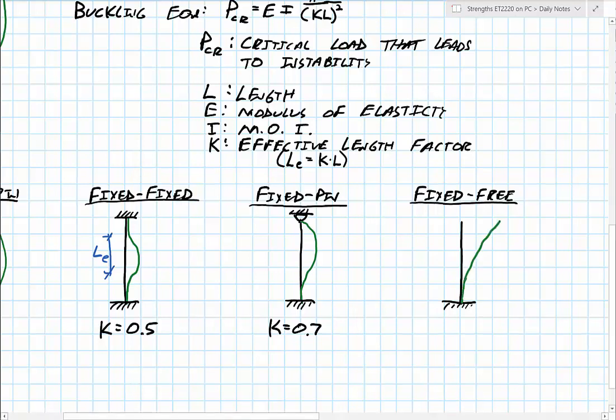How do I map out the overall effective length for this case? Well, the effective length would include if we carried it down the other direction. So it's going to get much bigger, so our k value is going to be greater than 1. And in fact, this is like half of the curve, so our k is going to be 2, giving an overall effective length of twice the height.